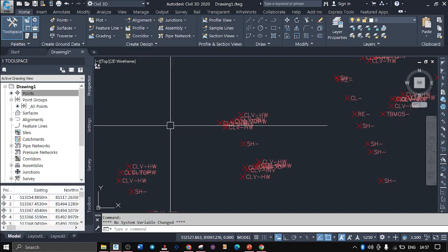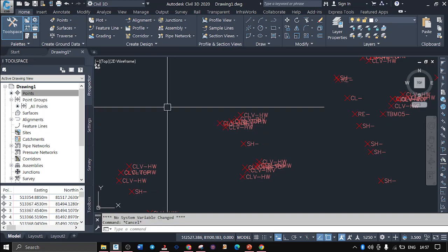Now, if you're drawing a road, you have like a 2-kilometer road, you have a very big chunk of points. We are going to sieve the center line. We are going to sieve a particular point with a different point description and put them in a different folder. We also get different points, we put them in a different folder. This is something really very important, so you should really write down.